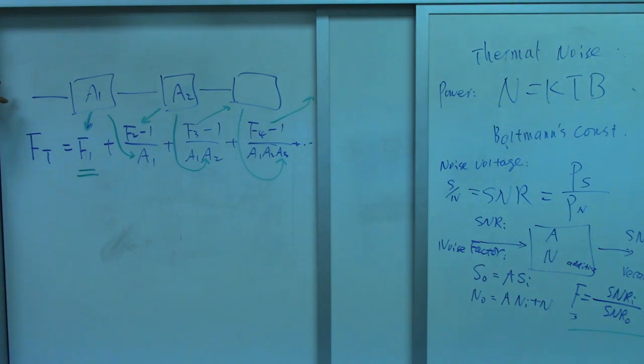Usually, you are going to use your best quality device in the pre-amplifier. For example, the low noise resistance or inductance or these IC chips. Why do you want to use that? Put your investment in the first stage. The gain is not necessarily large. We can use the gain equals 1 or very small, but that doesn't matter. That's not the purpose for the pre-amplifier.